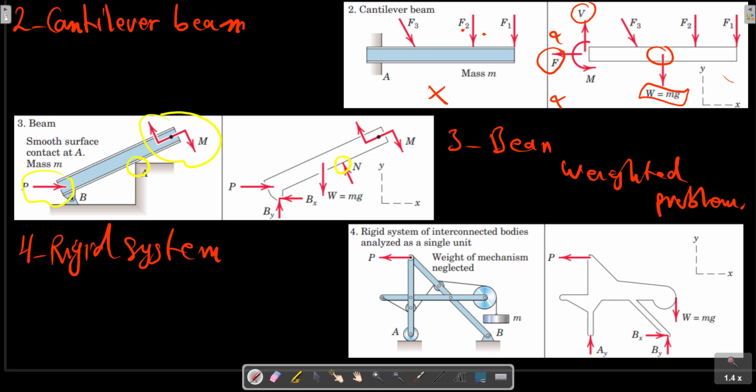Any one of many internal configurations for securing the cable loading from the mass m would be possible without affecting the external response of the mechanism as a whole. And this fact is brought out by the free body diagram. This hypothetical example is used to show that the forces internal to a rigid assembly of members do not influence the values of the external reactions as shown.